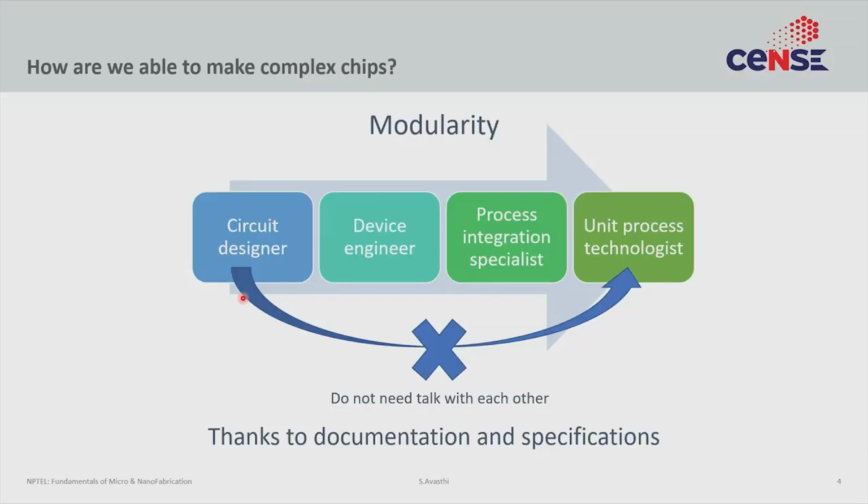So the documentation and specification is a very important aspect of process integration. A lot of students don't keep, for example, good lab notebooks with detailed notes of how they made the device. That's a very poor idea. That's a very poor habit. In general, have very good detailed documentation. You should make detailed, copious amounts of notes of how exactly that device got fabricated. A few months, a few years down the line, you will not remember the details and you will not be able to recreate the good data that you got because human memory is failing. The only way to ensure things survive is to make sure things are documented.